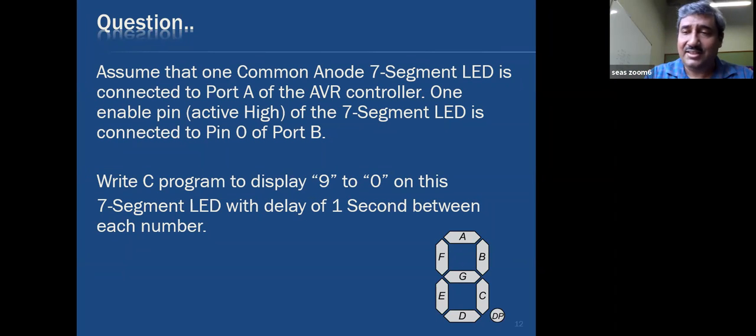And it would be interesting. You can see, yes, this is what we see on traffic lights and in many scenarios, when we count down the time. Maybe you can have a 1 second delay. So this will be the thing we'll take. So you understand the overall logic, right? We will send out the number, starting with the combination of zeros and ones to display 9, wait for a second, then send out the combination to display 8, wait for a second, 7, wait for a second, all the way to 0, then we can roll over if we want.